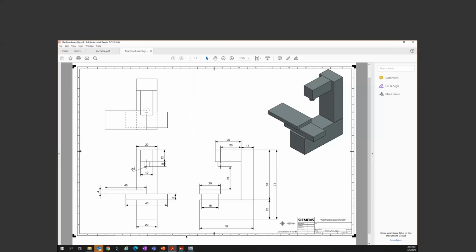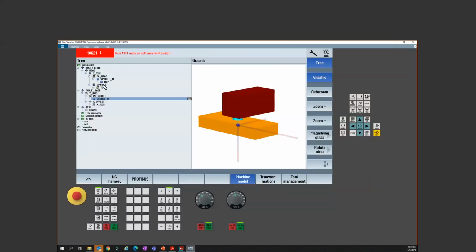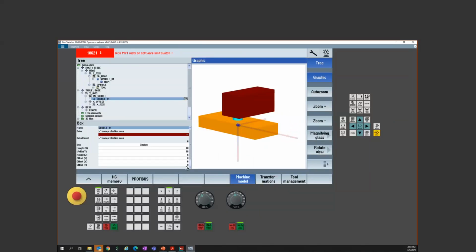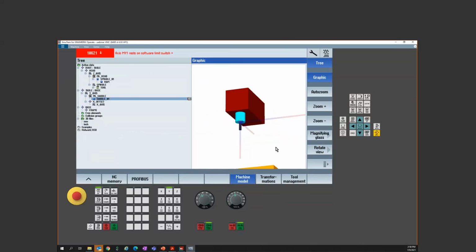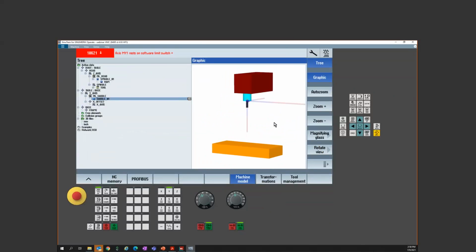So, boom, boom, boom. I know it's shifted in Z by this gap distance of 24, by the thickness of my table, which is 4, and then half of its thickness, which is another 3, right? So 24, 28, what's that get us to 31? So let's try that. So let's go saddle, Z offset, and it would be a negative 31.